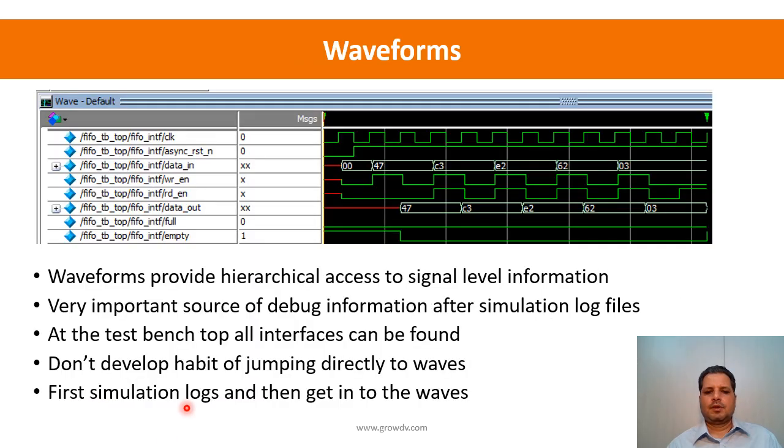log files. So after you have localized the interfaces and set of time regions where things have gone wrong, you would want to open the waveforms, right? And if you are not able to localize using the log files, you should go for waveforms. So waveforms provide hierarchical access to signal level information. You could go to any RTL hierarchy and look at what has happened. And waveforms are of course a very important source of debug information, but after simulation log files, especially for verification engineers,